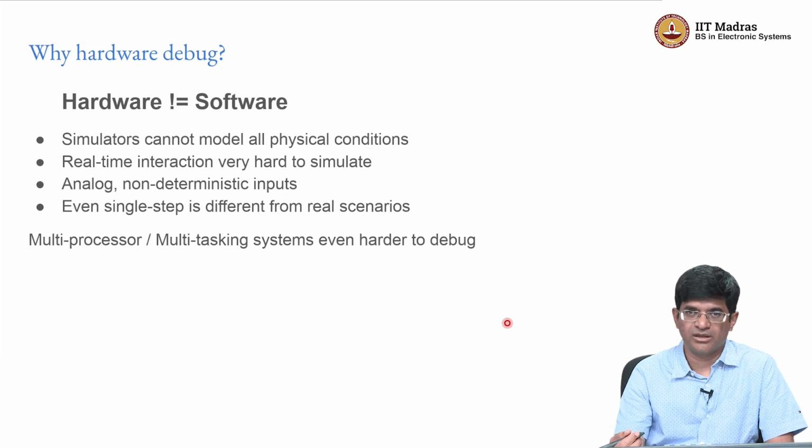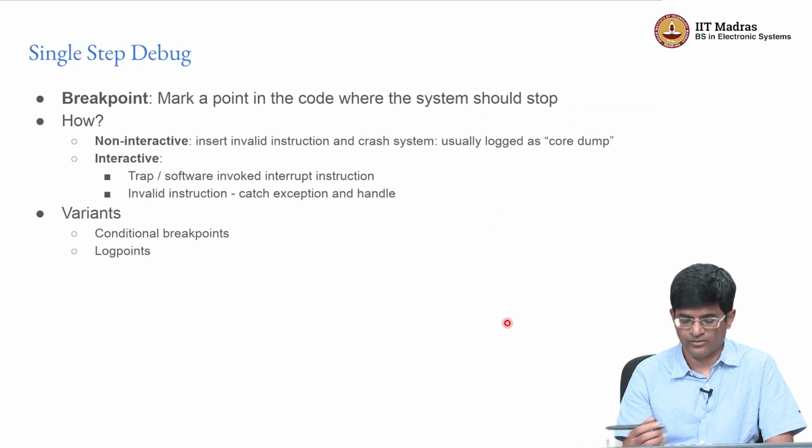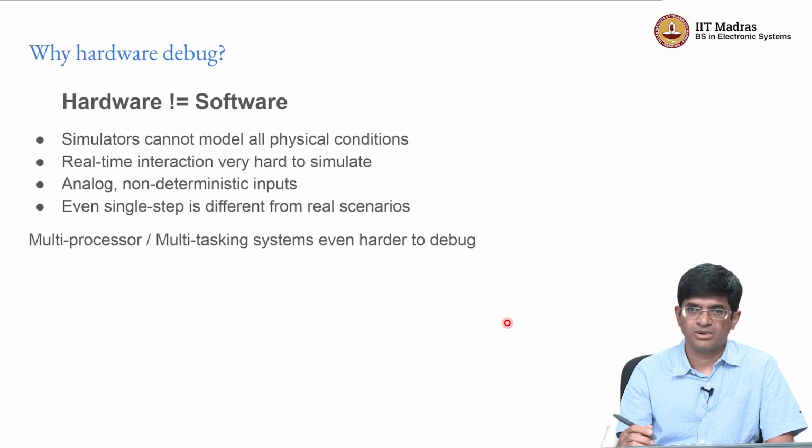So are analog inputs, right. Analog inputs to some extent can be modeled by just having an analog signal that is connected to the pin of the emulated CPU or the simulated CPU. But especially the moment you have some kind of non-deterministic or noisy behavior, that becomes harder to model in a way which is, well, deterministic, right? And by deterministic, what we mean is something that is repeatable, something that you have exact control over.